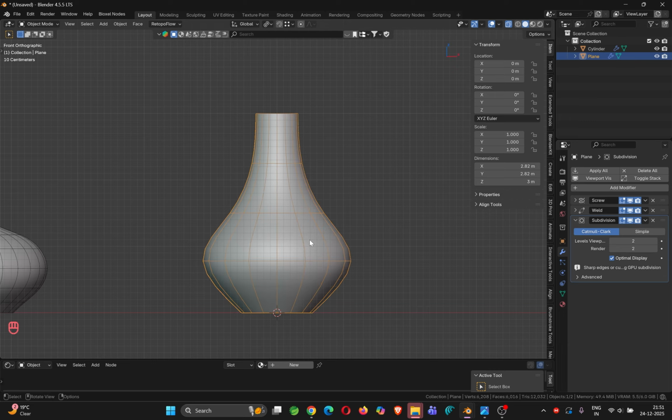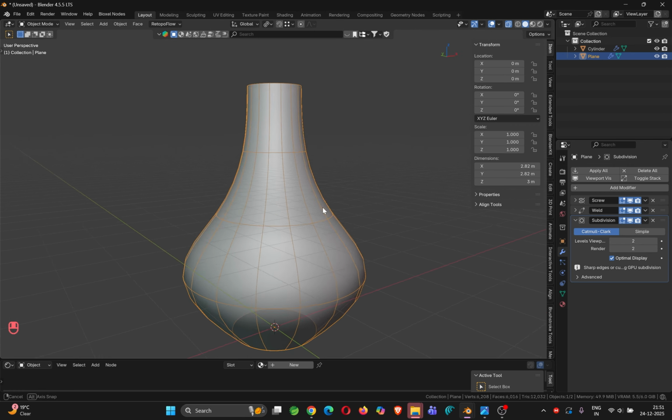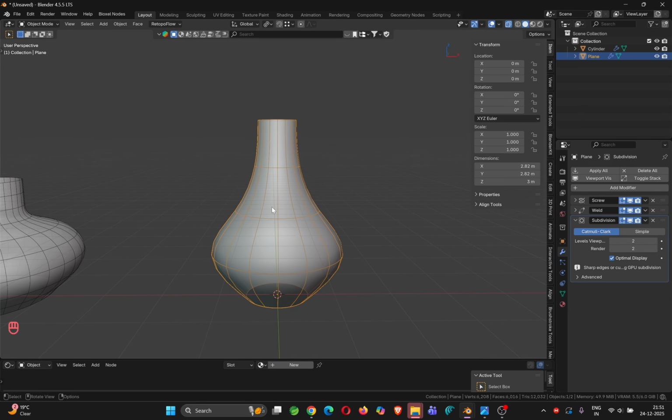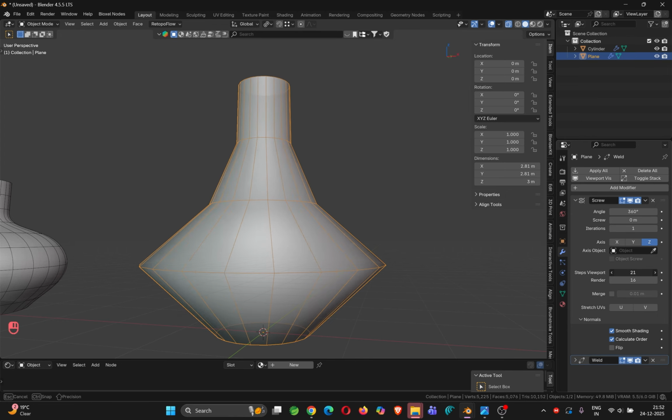For example, this is that wireframe model I am seeing now, right? Let me reduce that subdivision count to 1 or 2, 3, 4 like this. It will become smooth. But before committing, you don't know the amount of faces that you will be getting. For example, let me disable the subdivision for now. You can see it has created edges of, say, how many count? We know that it is 16. So if I increase it like this, I can use, say, 32 vertices here.